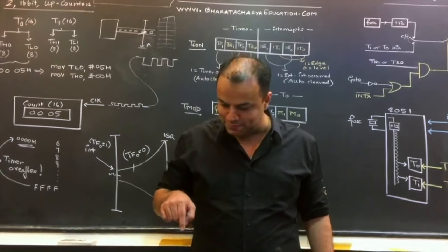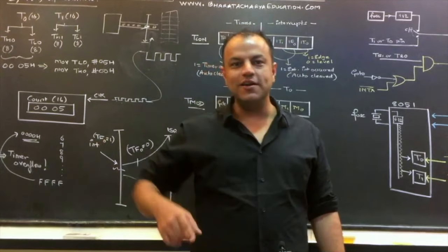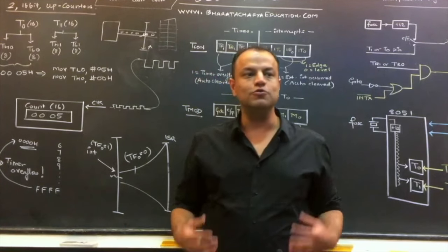Otherwise, people will be able to see and play with that light. So to avoid that, it is infrared. As you pass, you're cutting the light. As you cut the light, you're creating a pulse. Those pulses are given to the counter, which counts. So it's also a people counter.